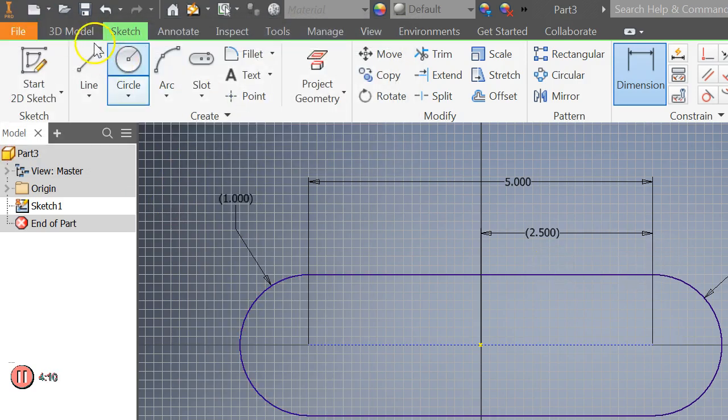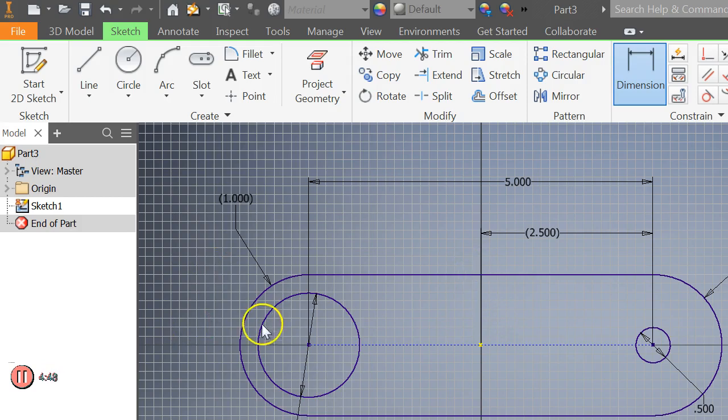And then I'm going to put some holes in here. One here, and then one here. When I did this before, I did not snap somehow to the center. So anytime that happens, you can add a concentric snap between here and here. But I think that snapped to that one, so we should be fine. It's 0.5, and this one is supposed to be equal to that one, so I'm going to point to it.